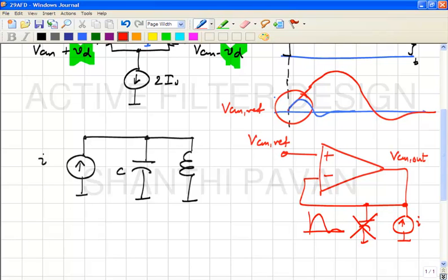What is internally happening is that it is not really a great voltage source to begin with, okay, but it is monitoring the difference between the output voltage and the reference and doing whatever it takes to keep the output voltage the same as the reference, right? That's what this negative feedback loop is doing, correct? However, this feedback loop has, speaking very loosely, a delay, right?